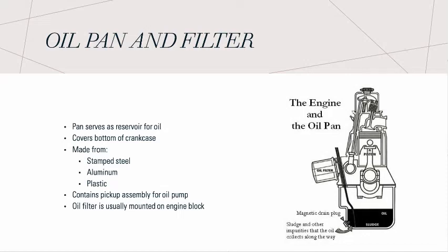An oil filter removes foreign bodies from the oil. The foreign bodies are typically items such as metal shavings, dirt, and dust. Clean oil is discharged from the filter and enters the engine. The oil lubricates all the engine's reciprocating or rotating parts and is then drained back to the oil sump. And normally the oil filter is mounted on the engine block.